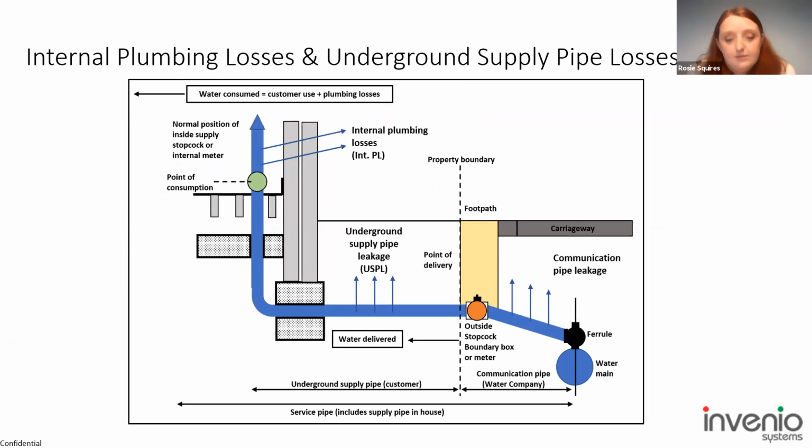Traditional leakage methods are usually acoustic, and metal transmits sound a lot better. When it is metal, you're more likely to hear that noise on the stopcock. If it's plastic, that can reduce the likelihood of hearing it. And if the length of the supply is longer, you can also struggle.